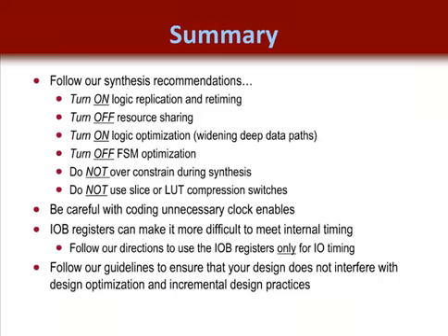Well, I tried to provide a detailed summary of the most important coding tips we provided in this module. In this module, we talked about some of the synthesis recommendations, and we told you to turn on logic replication and retiming, turn off resource sharing, turn on logic optimization, turn off finite state machine optimization, do not over-constrain during synthesis, and do not use slice or LUT compression switches. And these are, of course, for one main reason. We're trying to reduce the total number of registers our design uses, so that we give the tools flexibility to move logic around the FPGA to gain timing closure.